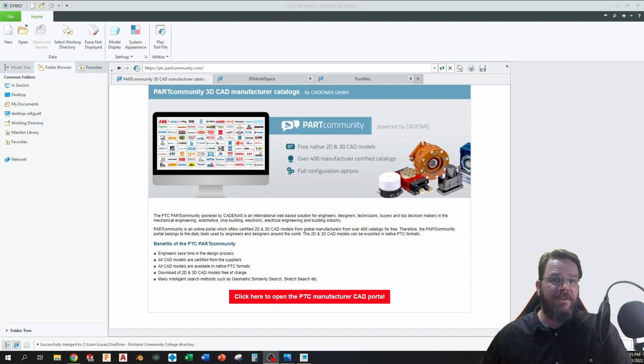So before we really get into it, I suppose the first thing we should do is talk about what parametric actually means. It's in the title of the software that we're using. You probably should know what it is. So basically, parametric means that you can take the geometric definitions of the design and change them at any time, whether it be changing them in the sketch while you're creating it, or coming back 6 months later and modifying a feature in the model tree.